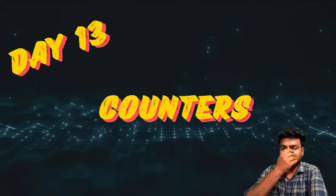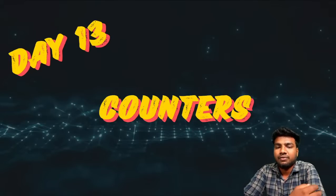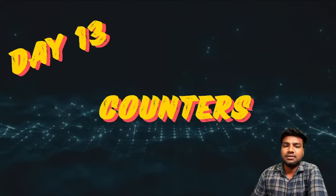We know that a counter is mainly used for counting purposes. It will start from 0 to 15, which means up counting. It can also do down counting, which means 15 to 0: 15, 14, and so on. We'll try to write the code in Verilog in this session: an up counter, a down counter, and then both up and down counting in the same Verilog code by using a mode signal. Based on the mode, it will go up counting or down counting.